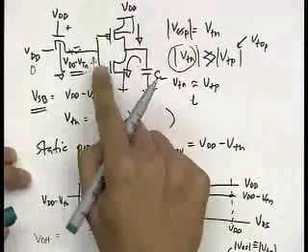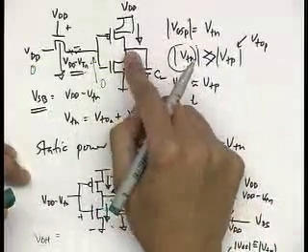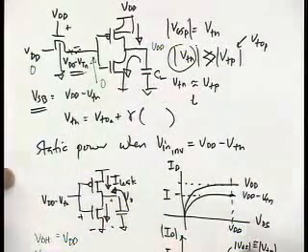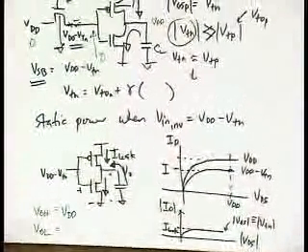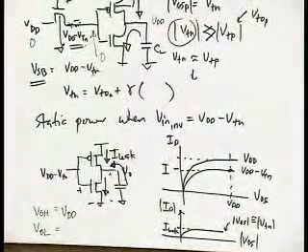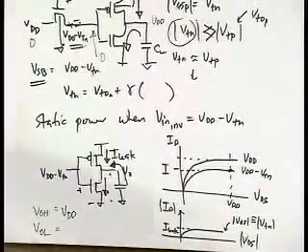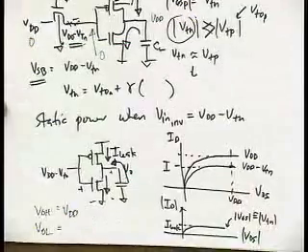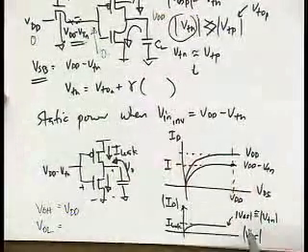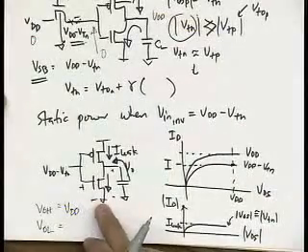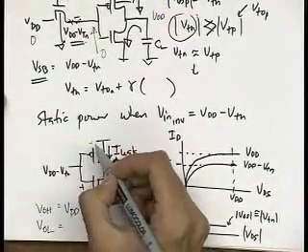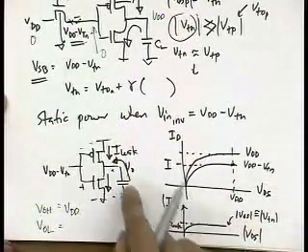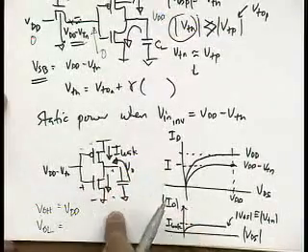So if I have a 0 in the input of the inverter, what's the output? VDD. So my VOH is VDD. What about my VOL? Will my VOL change? So what'll be my VOL? If you look at the curves here, this leakage current is a function of the gate overdrive here. Okay, so I get this, and you want to pull this down as low as possible.